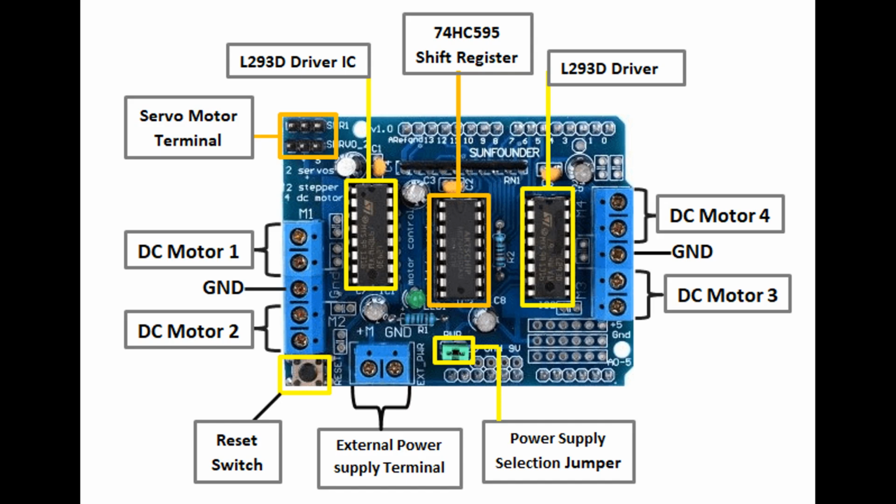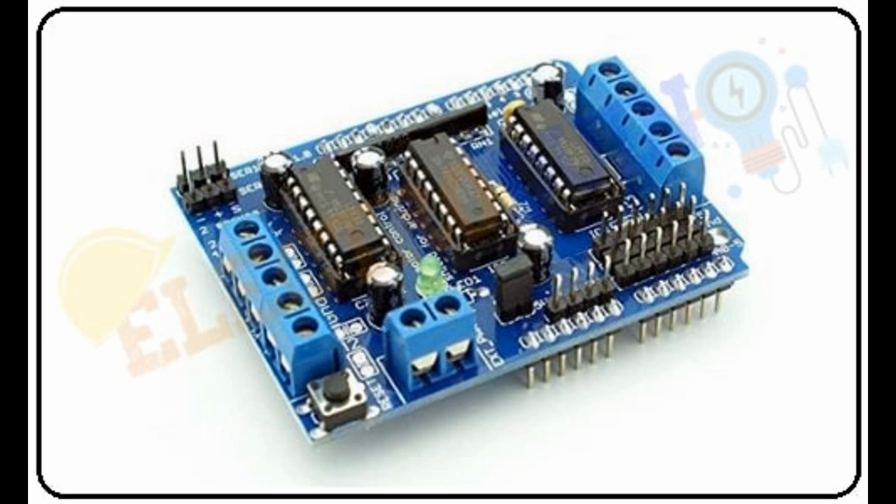Torque control. VFDs can also control the motor's torque by adjusting the voltage applied to the motor along with the frequency. This allows for smoother starts, stops, and load handling. Energy efficiency. VFDs can significantly improve energy efficiency by adjusting motor speed to match the load requirement, reducing power consumption compared to running motors at full speed constantly.